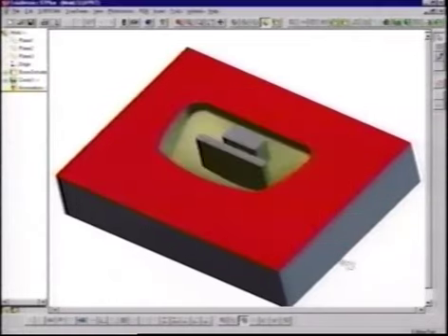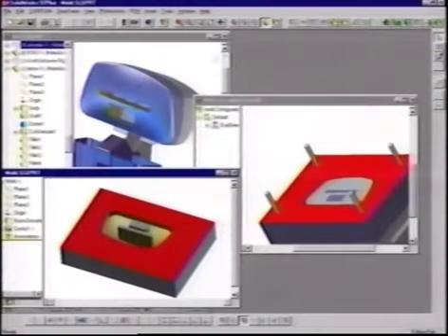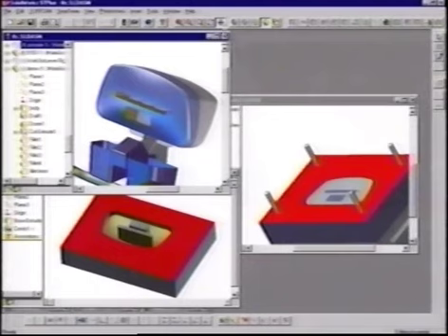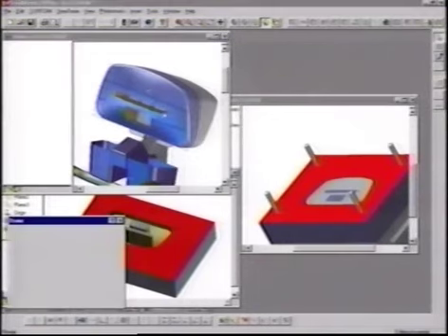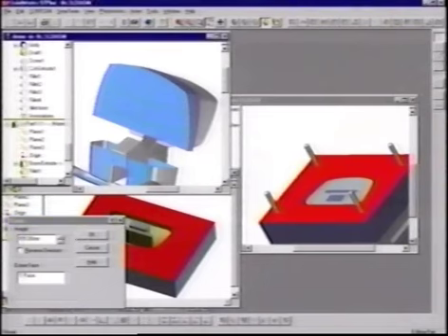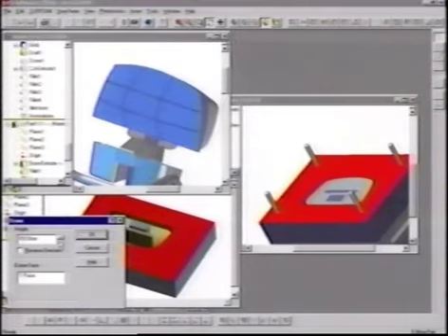Now let's say, as the tool designer and the manufacturing engineer have been doing their work, Joe's continued his work on the console part in the assembly. What we'd like to do is, we've looked at the design, we have this great shaded representation so we can evaluate how it appears. Maybe we don't like the fact that the shape is convex. We want to make it so it's more concave and give us more of a wraparound feel in the design. So Joe's going to go back and he's going to edit the dome feature that he was working on before. Again, he can control the magnitude of the curvature, and not only that, but the direction that it curves in as well.